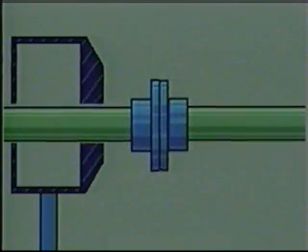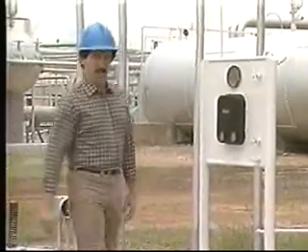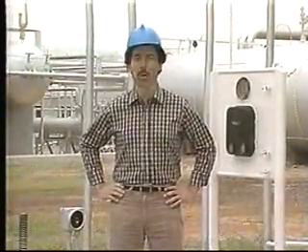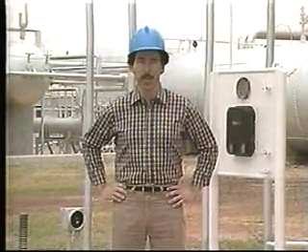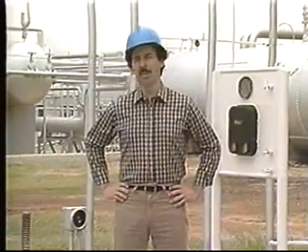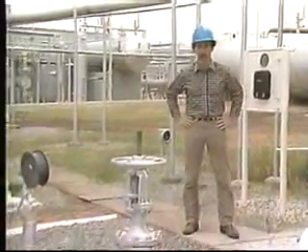If that vibration gets serious, it can put enough pressure on the shafts and couplings to break them. Vibration can do other damage too. It can cause bearings to wear, internal parts to rub, and impellers to become unbalanced. Now this is just to name a few of the problems. When any of these occur, we've got downtime and equipment that needs to be repaired.